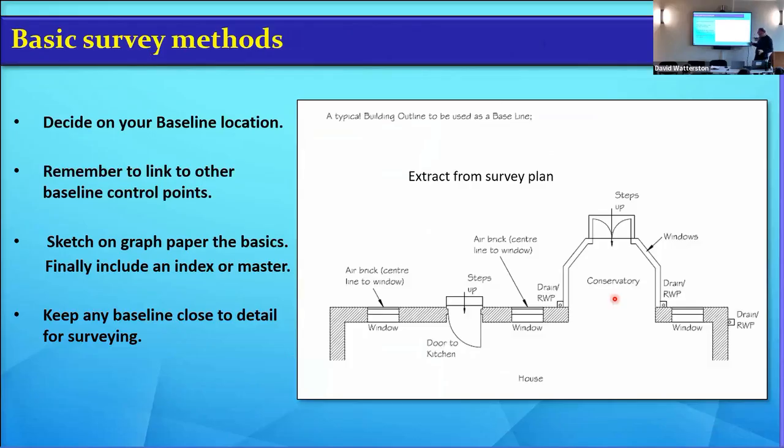So people would either go along the face of the house, the building, to measure, or they'll have an offset baseline. So they could eyeball and put a nail in there, take a measurement out there, put a nail up, a mark in there, and do the same distance off that end, exactly right angles. And then you'll have a baseline along the offset of the building, and then you can measure to the building face.